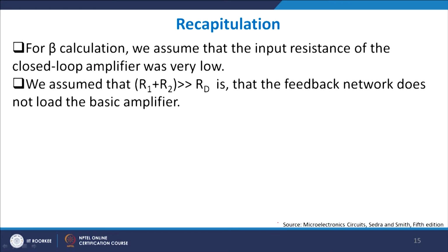Right. So, let me recapitulate what we did. Two important assumptions we have taken: that there is no loading of the amplifier or the feedback network. In reality, this is not true, you will always have some loading, however low it is, it is still there. The second thing is we have taken them to be almost independent of frequency, and therefore, our understanding here stands very well within the domain of the mid frequency band, where your gain is almost stable with respect to frequency.